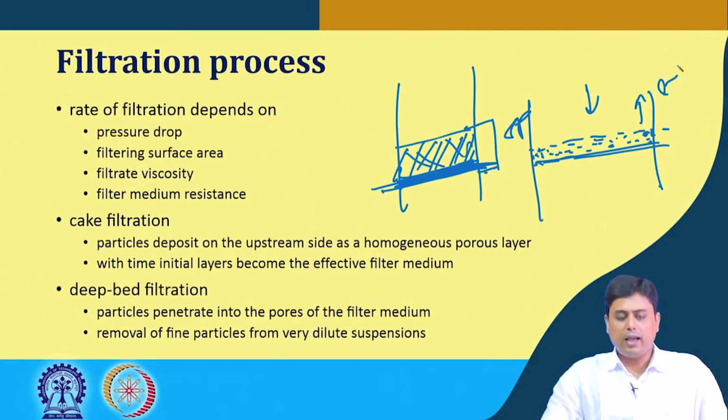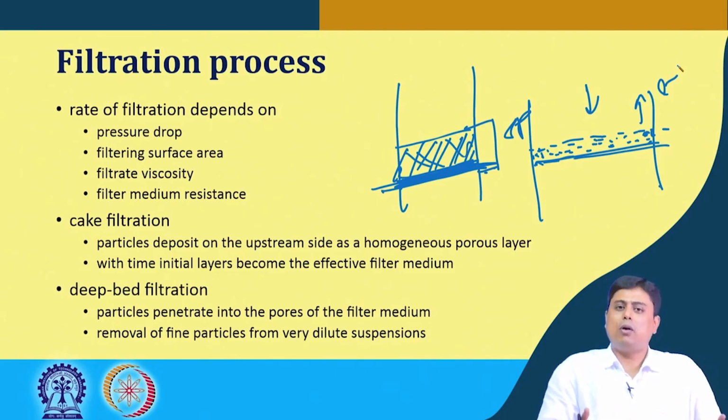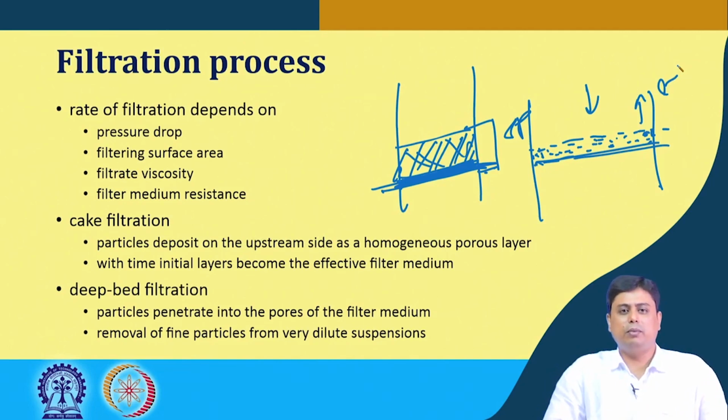And in cake filtration, opposite to this, you can understand we can have this cake clearly that we can scrape out from the upper surface of this filter media, and then that can be washed and dried to recover the solid particles. So which means when the solids are valuable, we can propose the cake filtration mechanism.